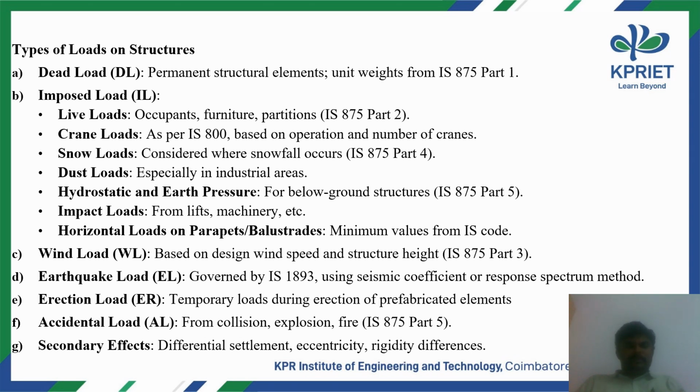And then apart from these loads, an additional one is accidental load, from collision, explosion and fire, which is unexpected. And the last one is secondary effects: differential settlement, eccentricity and rigidity differences.